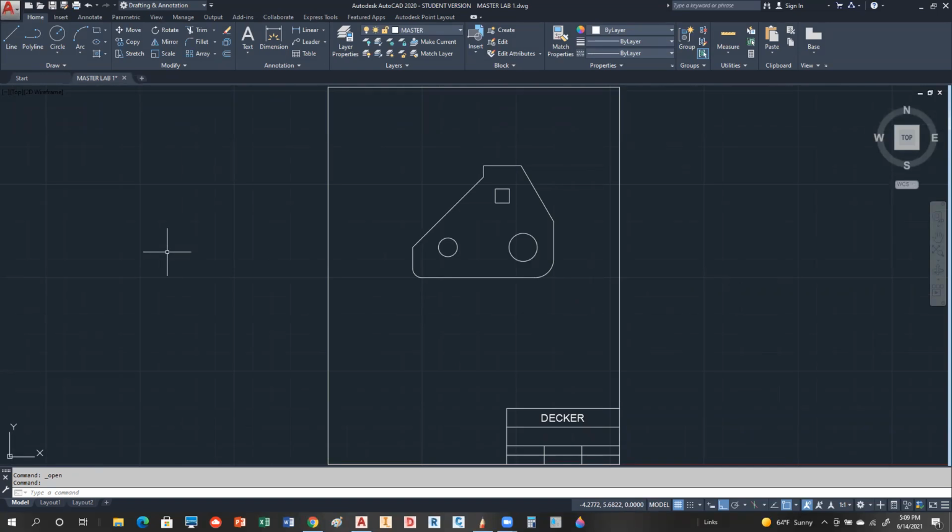By the way, I should mention there's, besides the BAK file, sometimes while you're working, you'll also see a DWL file. That's a lock file. That's a drawing lock. So if I open a drawing twice, or actually even while I'm working, there's a lock file that's generated. Sometimes you guys will save those lock files and try to open them up.